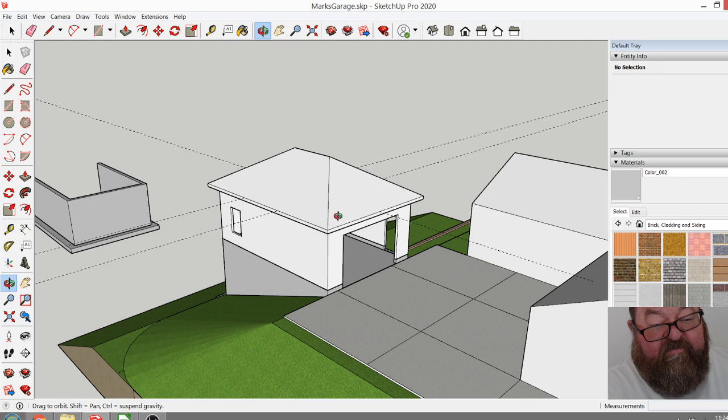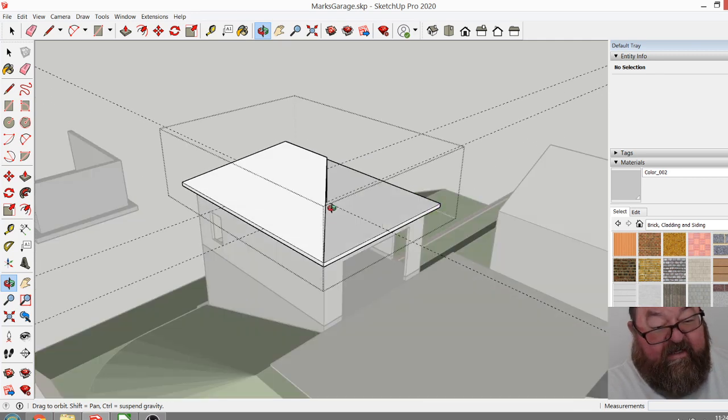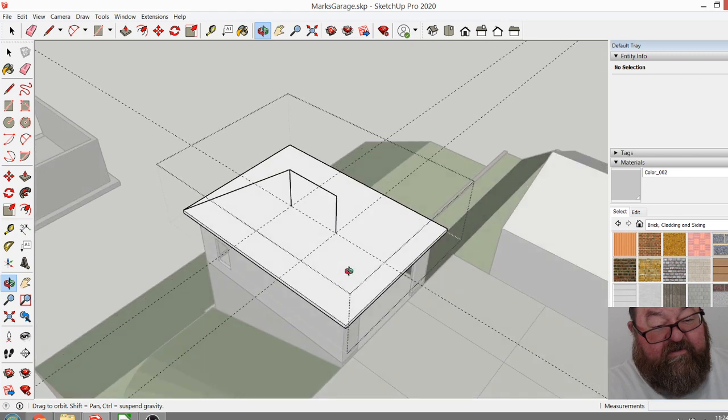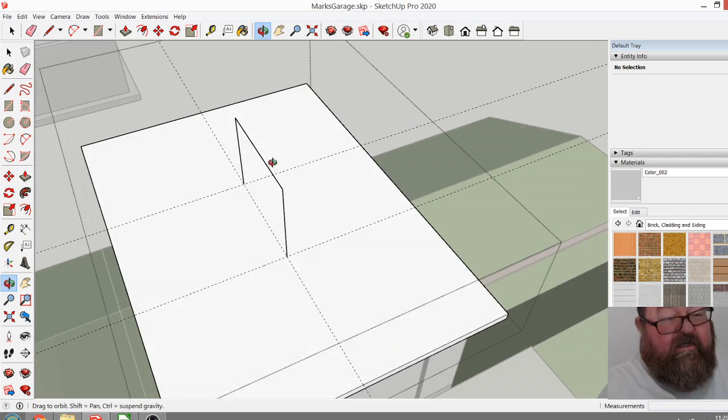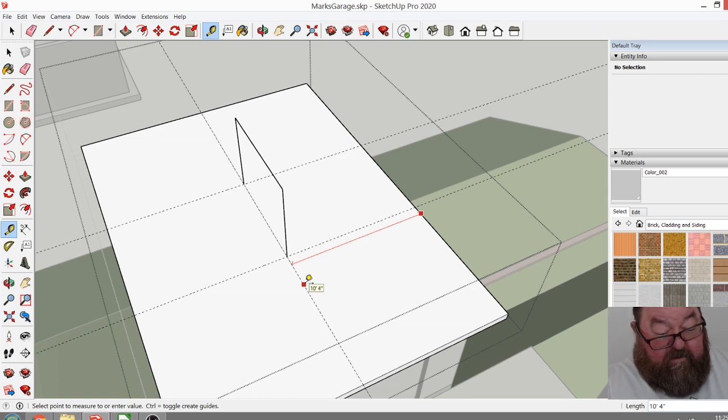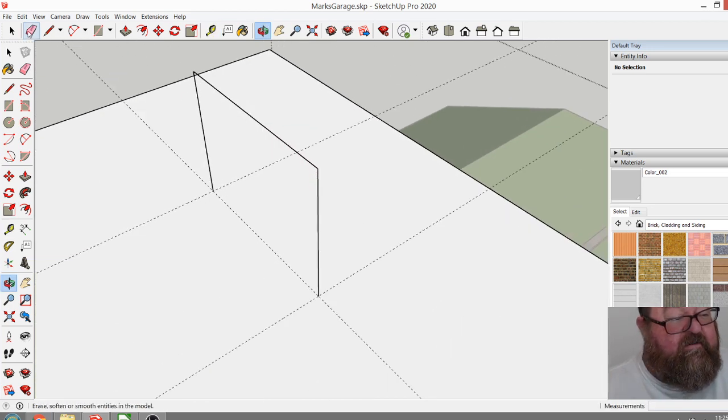The 4-in-12 seemed to be a bit low. Let's go back and make it an actual 5-in-12. Let's just be accurate here. And I'll get my calculator. I wish I could do all this stuff in my head, but let me just use a calculator. Got the wrong phone. So that's what you would do: 10.3 times 5. 51.5. So we'll just do that.